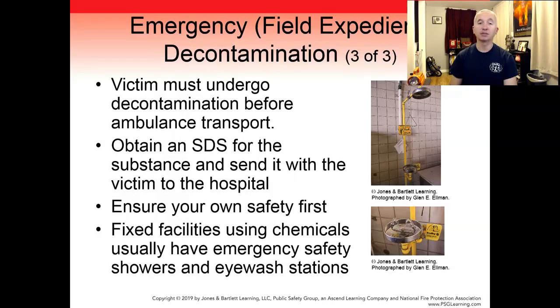Obtain an SDS of the substance to which the person has been exposed and send it to the hospital with the patient. Ensure your own safety before decontaminating others. Most facilities that use chemicals will have emergency safety showers and eye wash stations available to their employees.